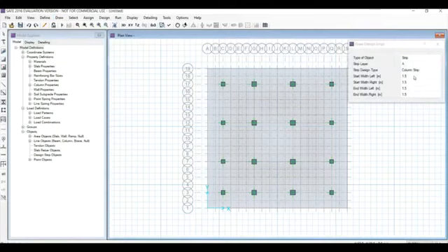Our least dimension is 18 meters, and we need at least 0.25 times the least dimension, and 0.25 times 18 is 1/4 of 18, which is 4.5. So start with 4.5, and again 4.5, 4.5, and 4.5. And now strip layer A and column strip.